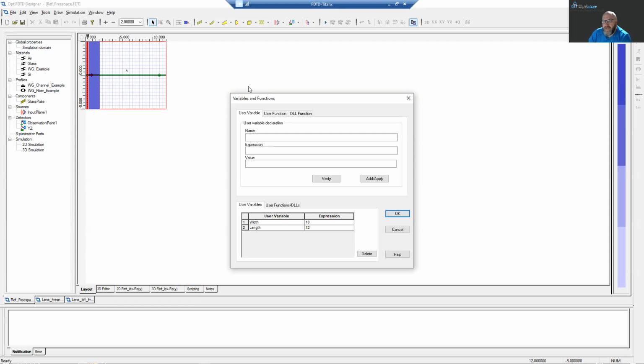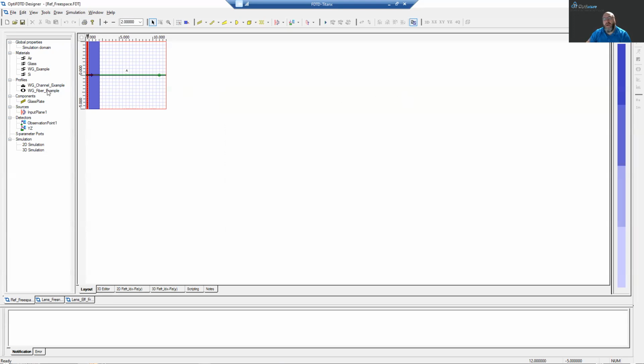This is the width of the simulation in the X and the Y axis, and then the length of the simulation along Z. Because the source and the observation area are going to use that width information, we make this a parameter so we can use that in all of the objects. So if you have to change it, you only change it in one spot. But we are not actually going to create each of these things in the same place here using the GUI. What we're going to do is we're going to do it using a script.